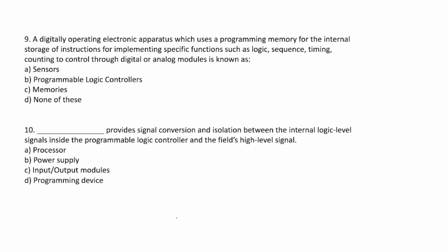Here comes the programmable logic controller. It is a digitally operating electronic apparatus that uses programming memory for internal storage of instructions for implementing specific functions such as logic, sequencing, timing, counting, and arithmetic, to control various types of machines or processes through digital or analog modules.